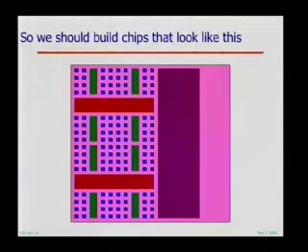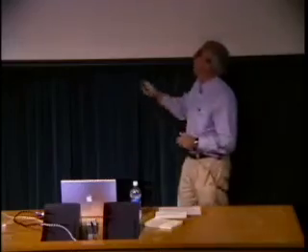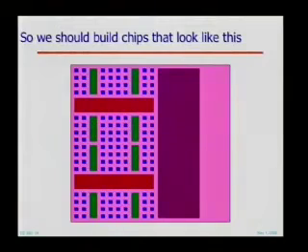Why does it need to be close to it? Because the capacity of the registers in the blue dots has to be large enough to cover the latency to the green rectangles, right? The size of a register file is driven by two things. It's driven by the need to supply what's downstream from it, and the need to tolerate the latency to what's upstream of it, to the next higher level in the hierarchy, right? If you try to go all the way off chip with this, that latency is too high. These register files would get really big and the whole thing breaks.